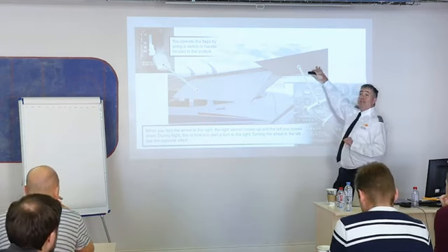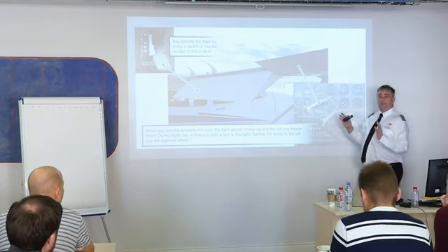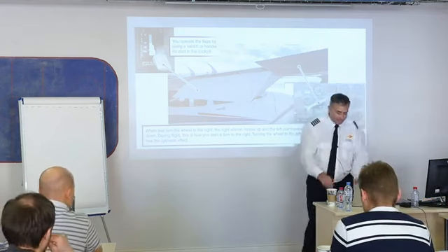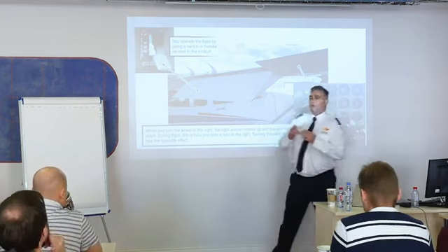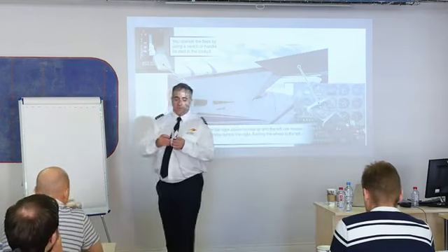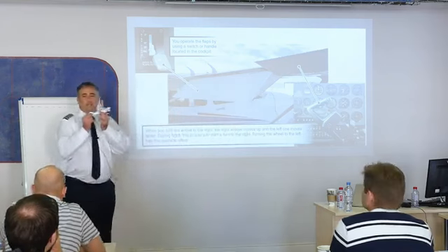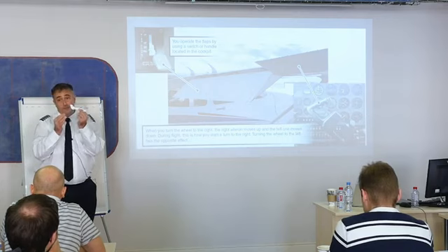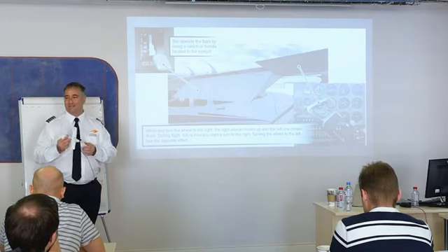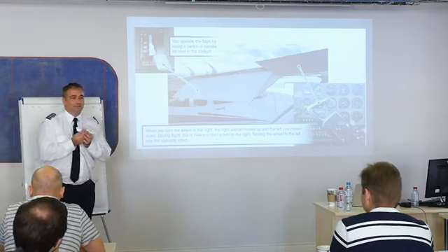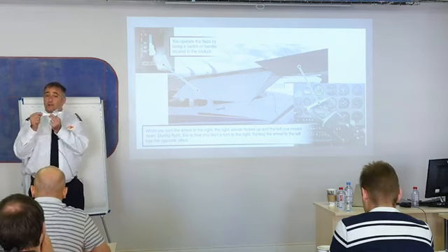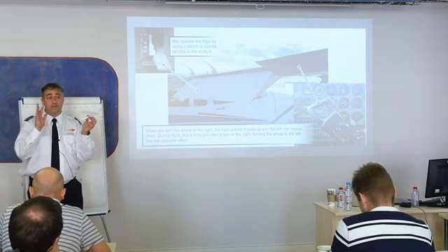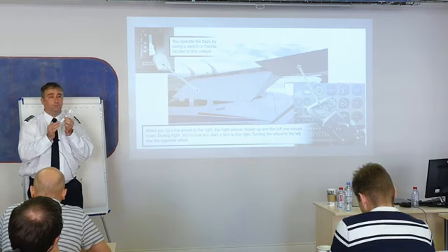All right, because the ailerons are on the outside of the wing, and it's important that I know flap, aileron, that's easy, but where are they at? They're built that way for a reason. And the reason is because the airplane is able to fly at cruise speed, relatively fast. Well, we could say relatively fast, 120, all right. All right, cruise speed, or I could fly it very slow. I could fly somewhere around 35, 40 knots, right? Very, very slow.